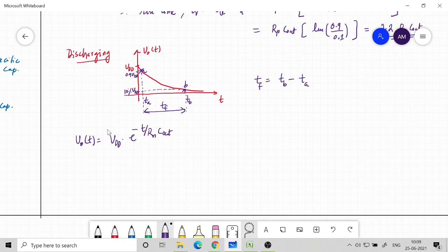That is also something you need to consider while designing the inverter. Designing means all the design parameters you have to fix accordingly. I classified the parameters as design parameters and process parameters. Process parameters are given to us by the foundry. We cannot change them, but what we can modify are the design parameters. So there are a few of them which you can decide accordingly, and your Rn and Rp will be fixed.